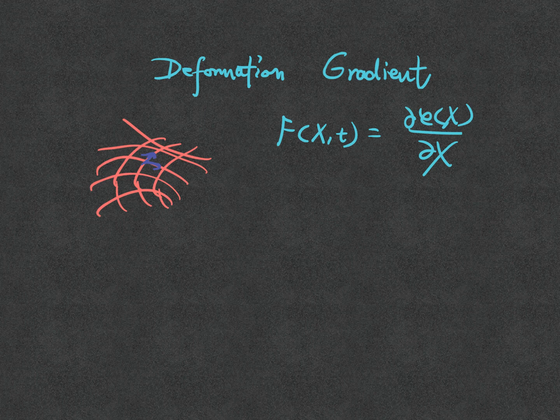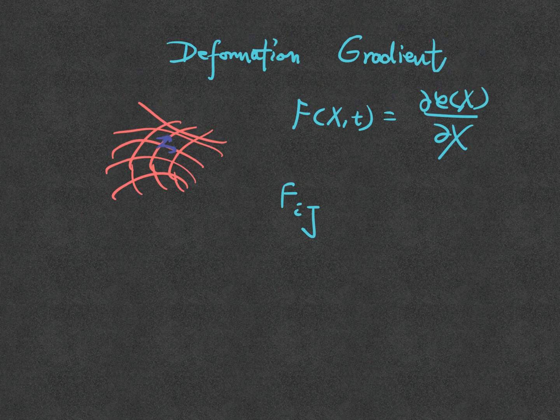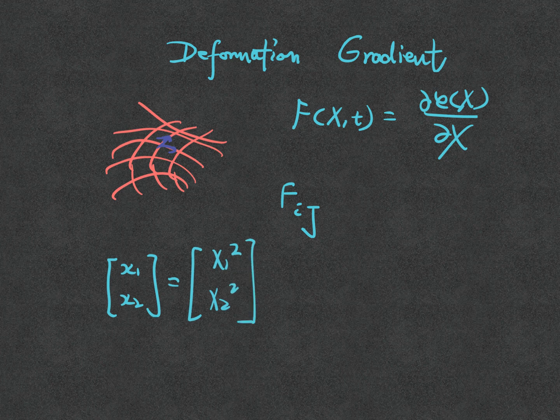Now, because it's the linear deformation, you can also write F. Oftentimes you write F_iJ as a component, and J is in capital letter. Okay, do you know why? Because the deformation itself could be nonlinear, but if I'm linearizing it, I would always get Fx plus c. Does that make sense? Okay, let me give you an example. Let's say I just consider 2D again. The mapping of x1, x2 is equal to x1 squared plus x2 squared. Okay, does that make sense?